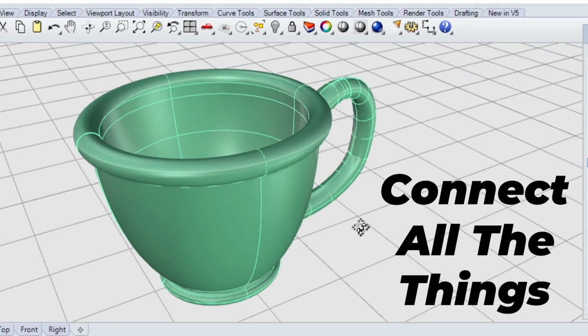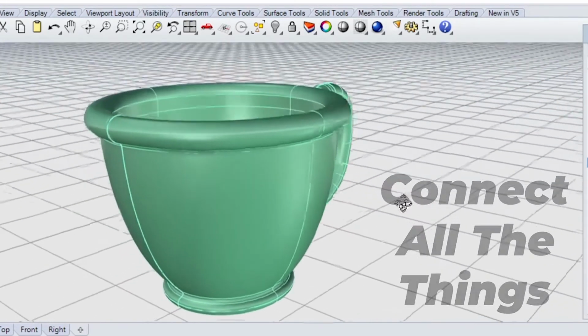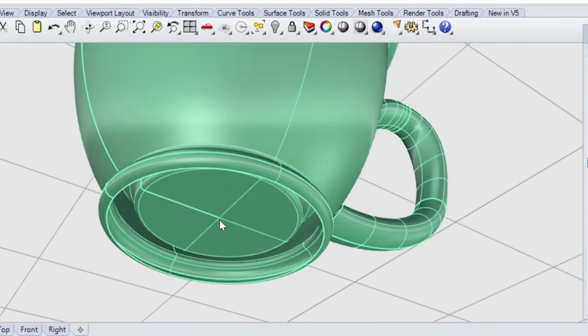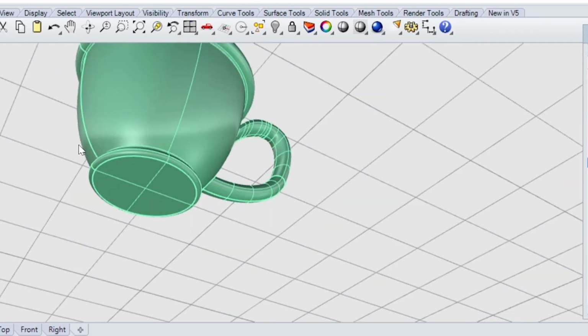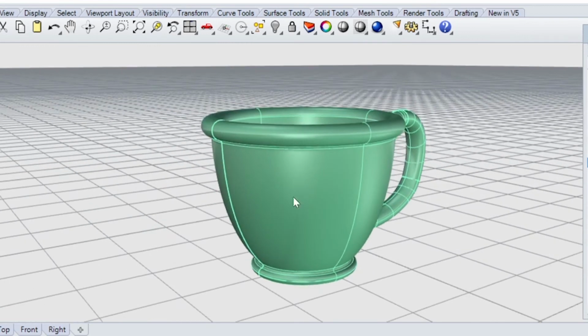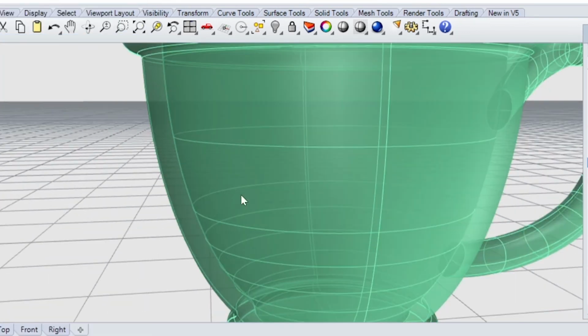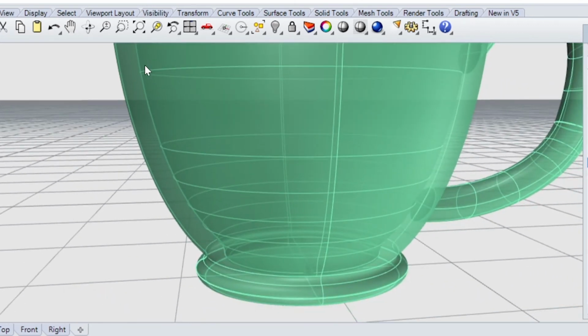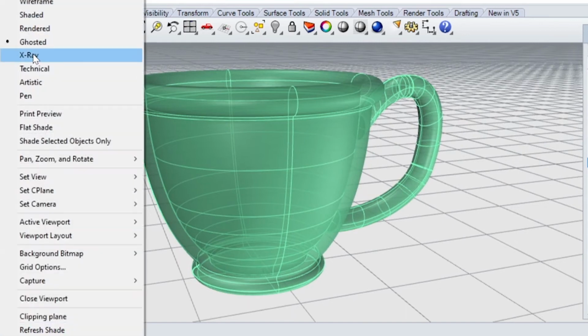Now, let's also review everything that we've covered up to this point. Is this object represented on all sides? Well, looks like no. Let's fill in that bottom. Excellent. Does this object have a real wall thickness? Well, let's jump into this, what we call a ghost view. And if we look inside this, we can see indeed there is an interior wall and an exterior wall, and at least appear to have a thickness that a printer should be pretty happy with.